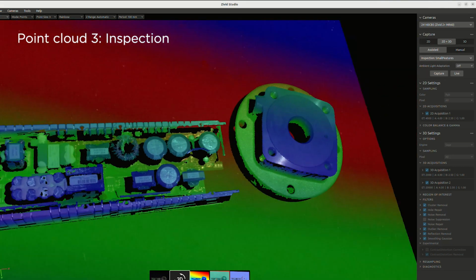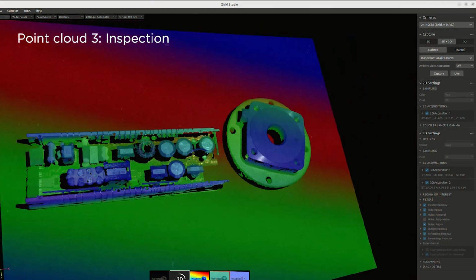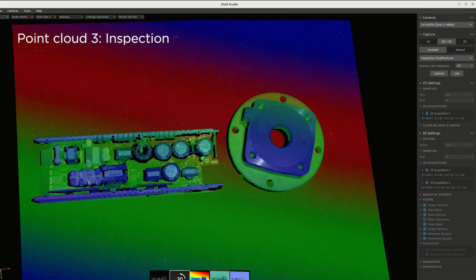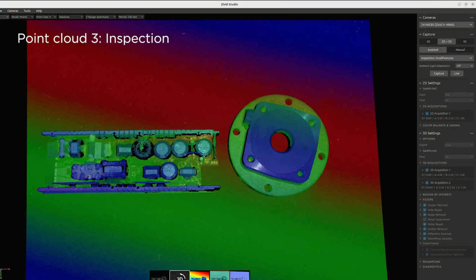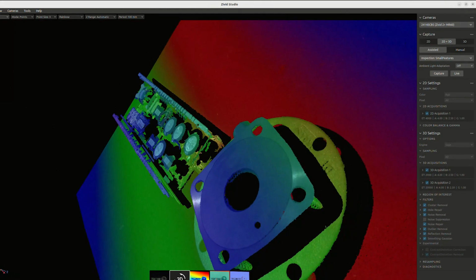When we are in inspection, the camera is mounted on the arm, and here we can talk about robot mounting flexibility, because the closer you are, the better it is. And for inspection, the MR60 is the best fit you can have, which means you have the focus distance at 60 centimeters. And every time you want to inspect, you can basically control the working distance you're having while capturing with the cameras.